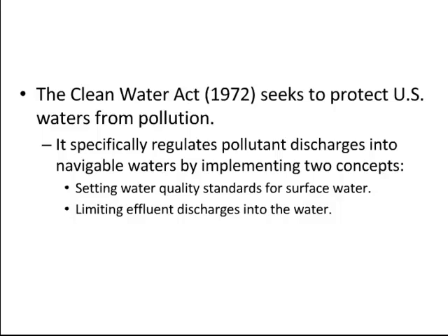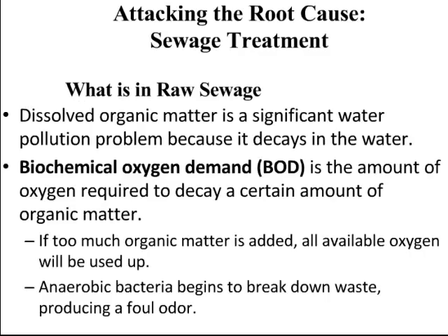So it's going to say that the city of Milledgeville, right here where GMC is, can only put so much sewage into a waterway. And it's not actually the sewage it's talking about, it's an item called BOD, which is biochemical or biological oxygen demand. So our Clean Water Act is going to limit how much of a pollutant can actually be released into a waterway.